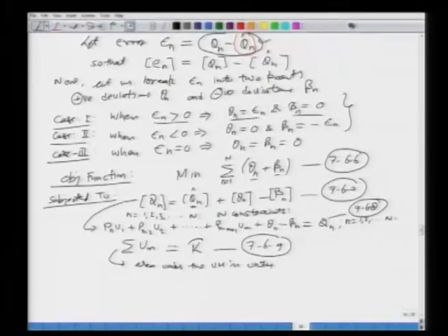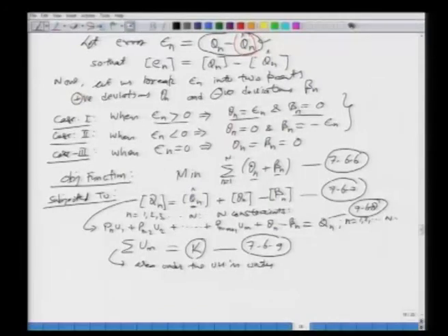What is this k by the way then? This k is nothing but, after you convert the units, the area of the catchment in square kilometers and depth of rainfall and so on. So, this is just taking care of that unit conversion, so that this is equal to some constant corresponding to area under the unit hydrograph equal to 1, or 1 centimeter of depth. Okay.